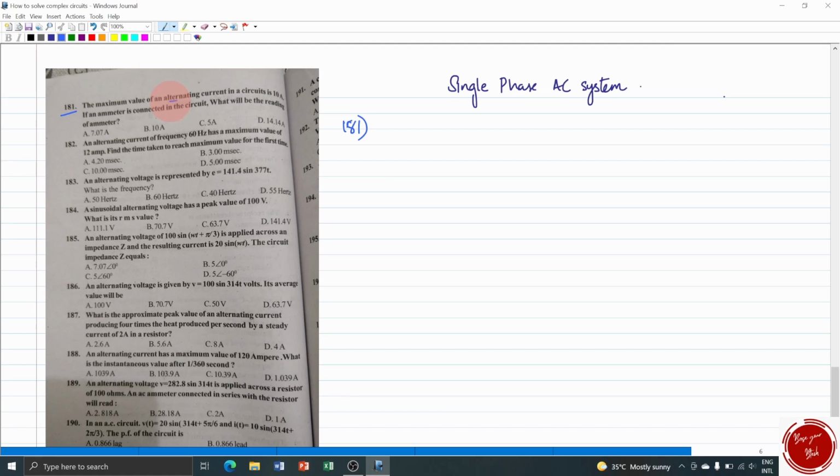So it is an alternating current, that is, any alternating quantity, which is a sinusoidal waveform. Let this be A, this is the maximum value AM, and this is the time period T. So this sinusoidal representation is: A, on the y-axis, is equal to the maximum value AM sine 2 pi by T into t, where T is the time period.